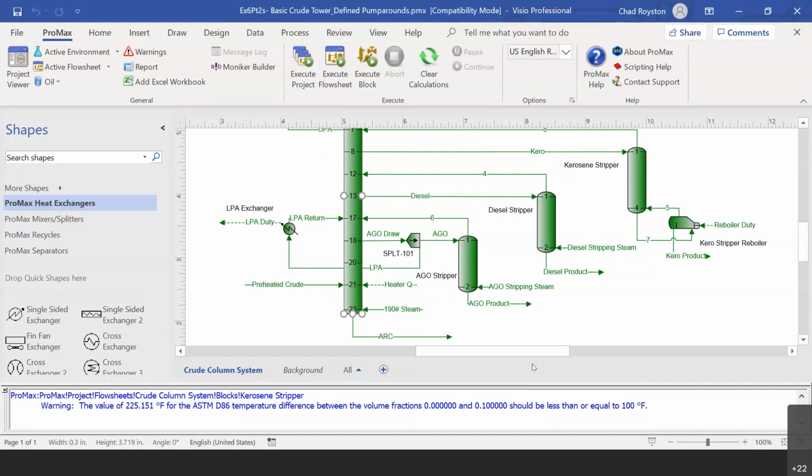You know, we say diesel yield optimization, diesel yield maximization. Certainly, you're going to be dependent on your crude assay. You can't take more than exists, okay? Which is one reason I wanted to show the TPP splitter, to give you an idea as to what the maximum theoretical yields might be for the oil given its boiling range.